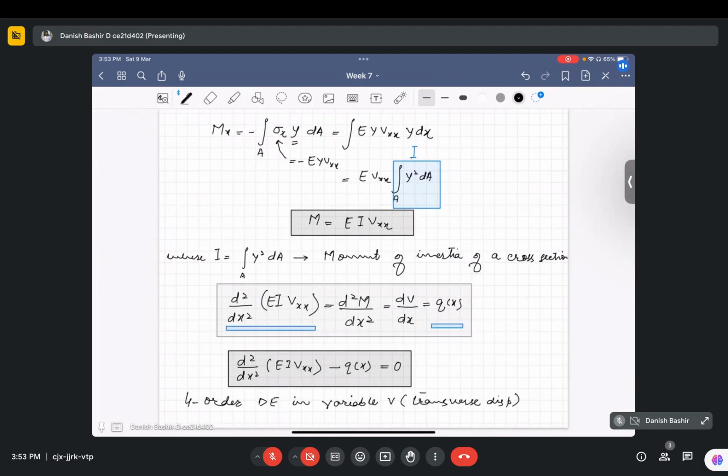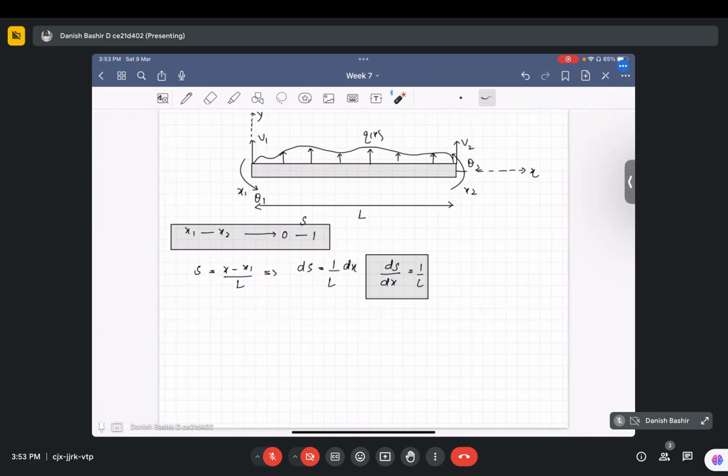So the beam equation is actually a fourth order differential equation. So for one given element, if we have to assume the trial solution, it should be of at least degree 3, that is, a cubic polynomial, to satisfy the differential equation. So let us assume the trial solution for the beam element in terms of transverse displacement, with s as variable, to be a naught plus a1 s plus a2 s square plus a3 s cube. So our dv by ds will come out to be dv by dx. We have to find dv by dx.